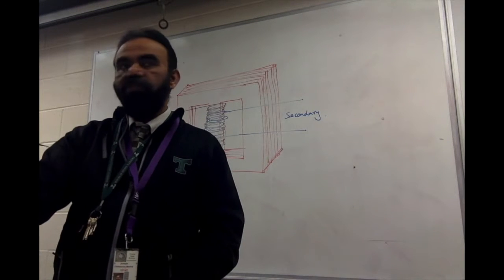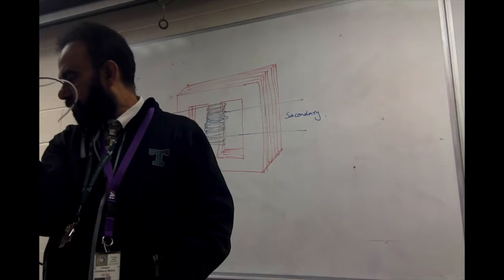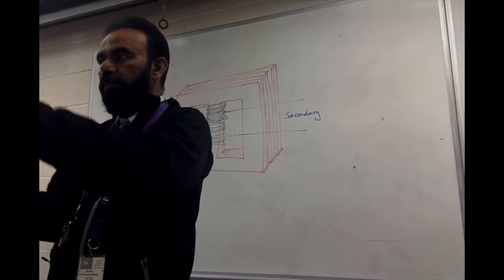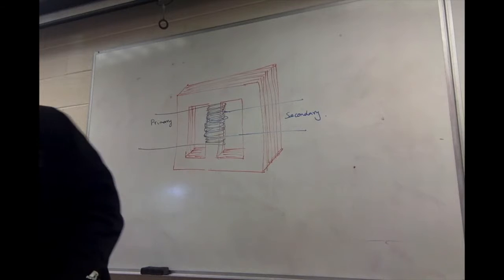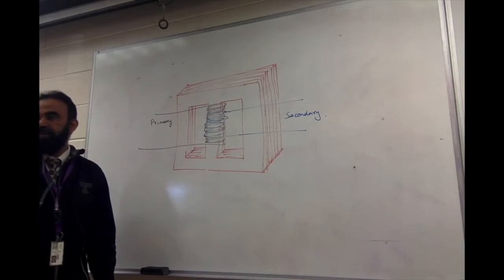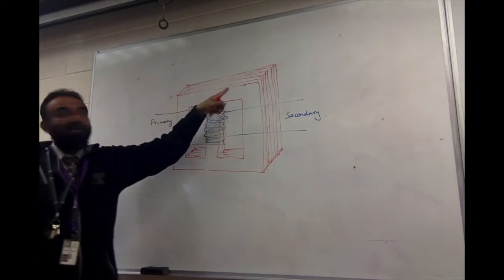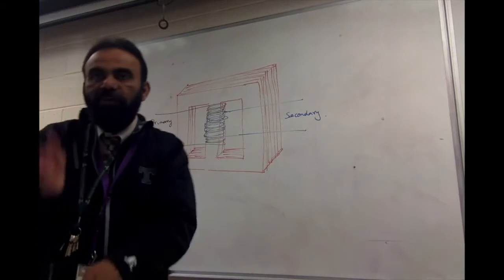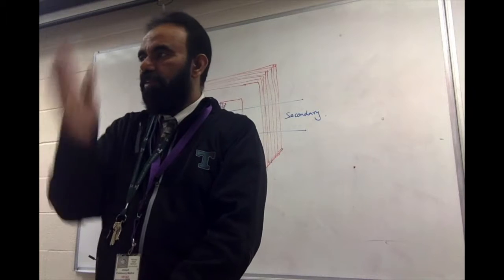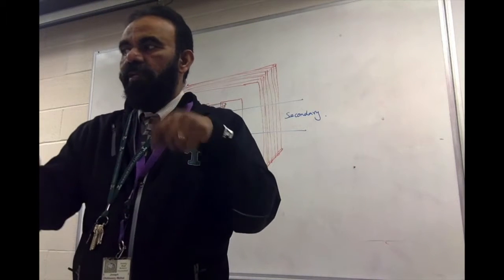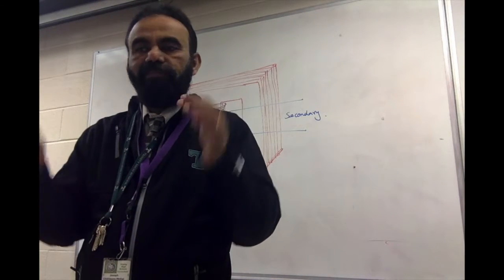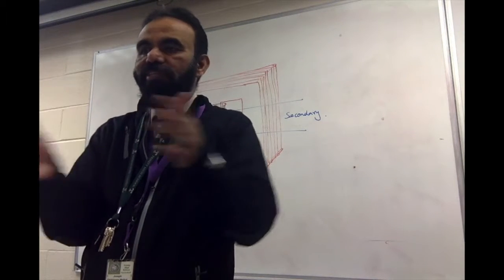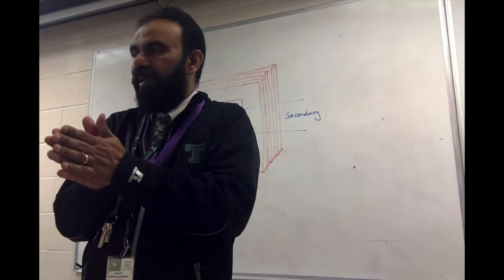If you want to have a look at it once again, this one. Did I pass this? No. Look. Did I pass it? Not today. You did. Okay. So you can closely look at it. This is what you see. And these are sheets of the core, split into fine sheets, and those sheets are dipped into varnish, and the varnish dipped sheets are non-conducting to each other, and they stack them together and pack it properly.